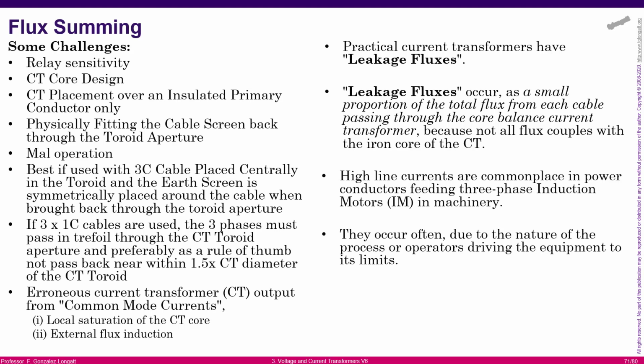Because the zero sequence components will appear when there is an imbalance, but in some applications that zero sequence can be small or bigger depending on the grounding connection of neutral points, okay? Installing these kinds of transformers in order to perform the flux summing can be done for low power applications. I mean, if you have low voltage and you have cables with insulation, you can put 3 cables together and you can install the transformer. However, if you are working in high voltage, that is not necessarily an option. And the reason is because you need insulation, and the distances should be so big that it is almost forbidden to use